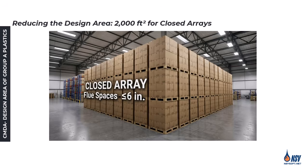These restricted flue spaces limit air movement deep within the pile, starving the fire of oxygen and allowing us to effectively control the hazard with a smaller design area. However, we must exercise extreme caution before relying on this reduction. Closed arrays are very difficult to maintain in active day-to-day warehouse operations.